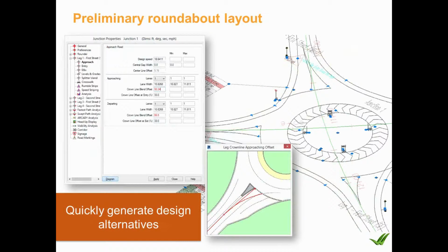It also has tools for generating parking lot layout information as well as roundabouts. One of the nice features that comes with the roundabout is, if you've ever done roundabouts in Civil 3D, you know that it has the roundabout tool and it does it in 2D, but in order to make it 3D, you have to go through quite a few extra steps to generate the assemblies, the corridors, and targeting, things like that. This will actually generate all of the alignments, offsets, profiles, corridors, and everything else. So that's really nice. And it's dynamic, so if you decide to move the roundabout, move any of the lanes, adjust the angles on them, everything updates. It also does pavement markings and signage, so that's kind of nice also.